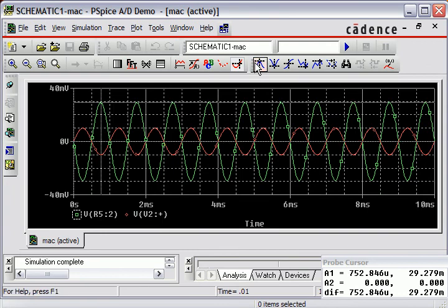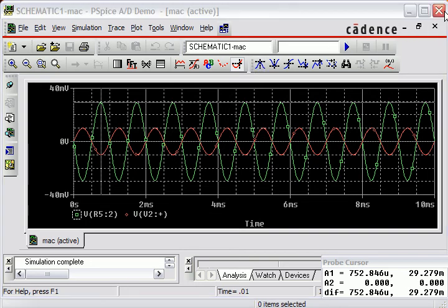Now let's go ahead and measure the peak voltage, and we can see that it dropped down in half. So using the idea of the voltage divider, we can tell that our output impedance is actually about 5K.